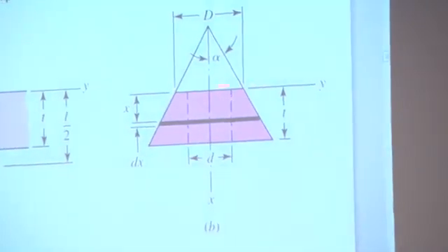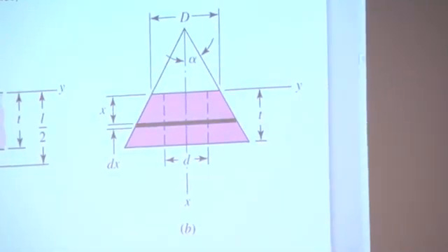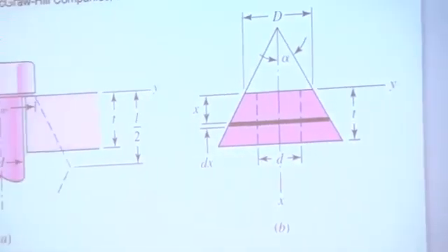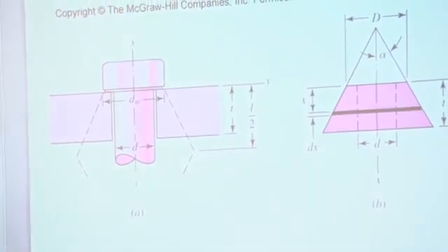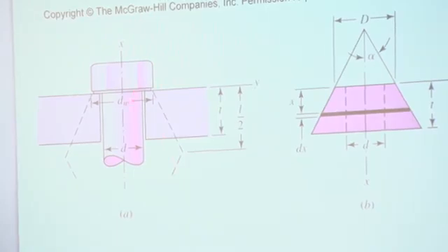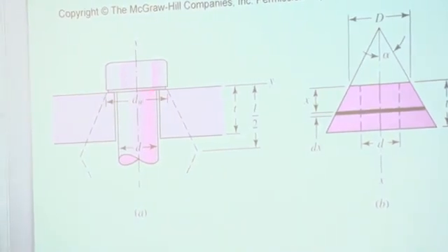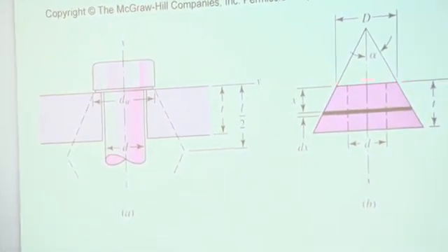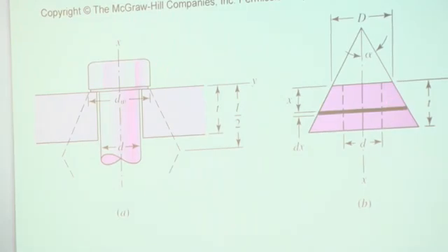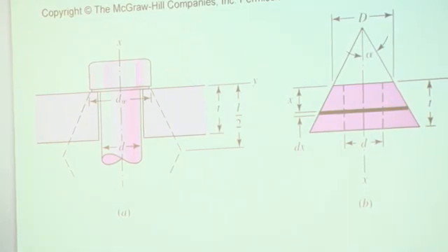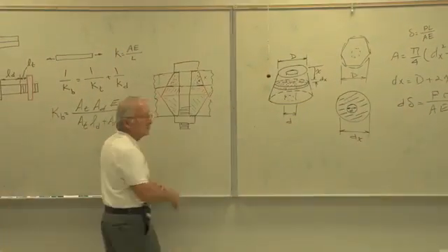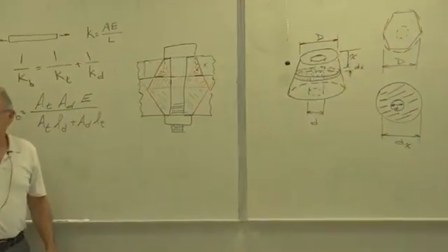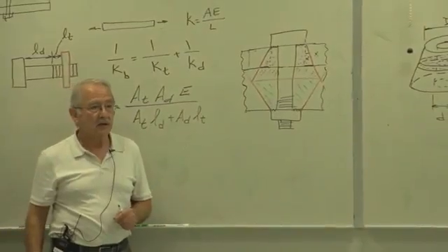So the small diameter here is equal to this diameter, also called the diameter of the washer, and you can take it approximately as 1.5 times the bolt diameter. That's just more or less the same as that. But if I'm going to calculate this for this middle part, it's equal to that. It's not D at the top.